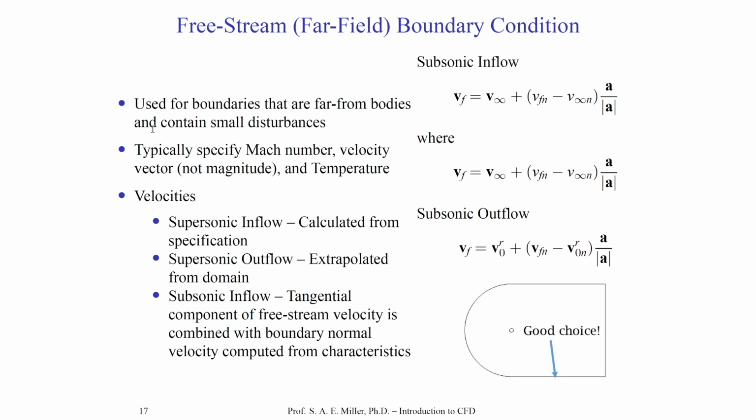So if you specify the so-called free stream or far-field boundary conditions, which are available in almost all excellent CFD solvers, especially in aerospace engineering, you have to make them very far away from the boundaries. For example, on the lower right, I've shown a cylinder in a cross-flow. This outer line is indeed where we would set the far-field boundary condition.